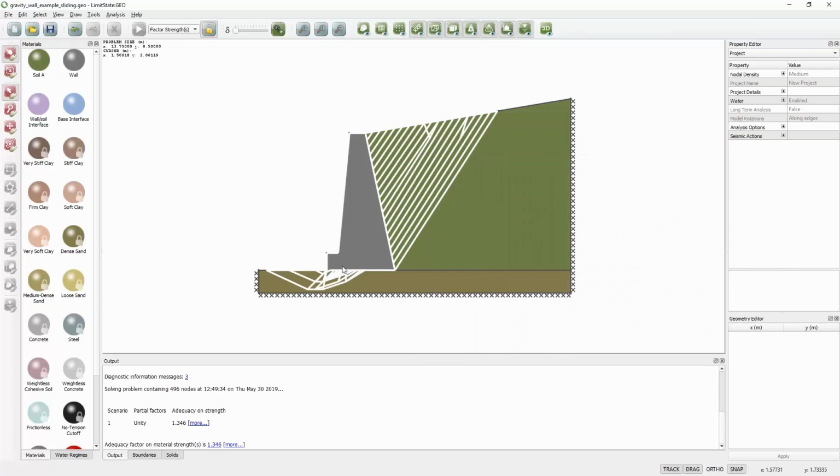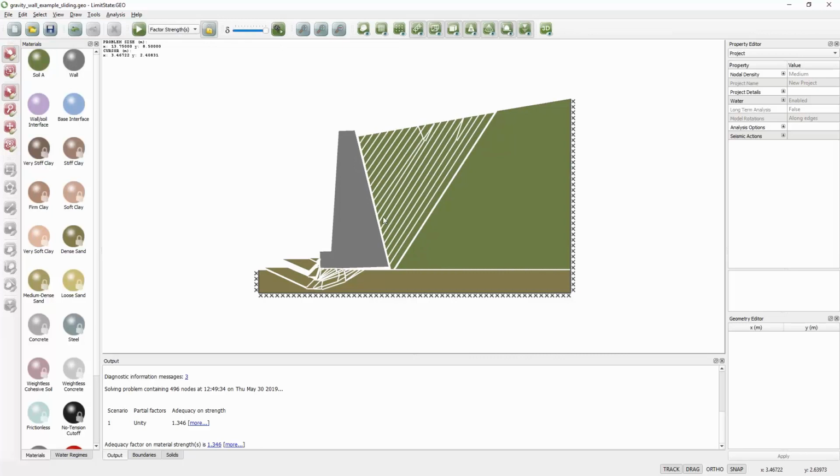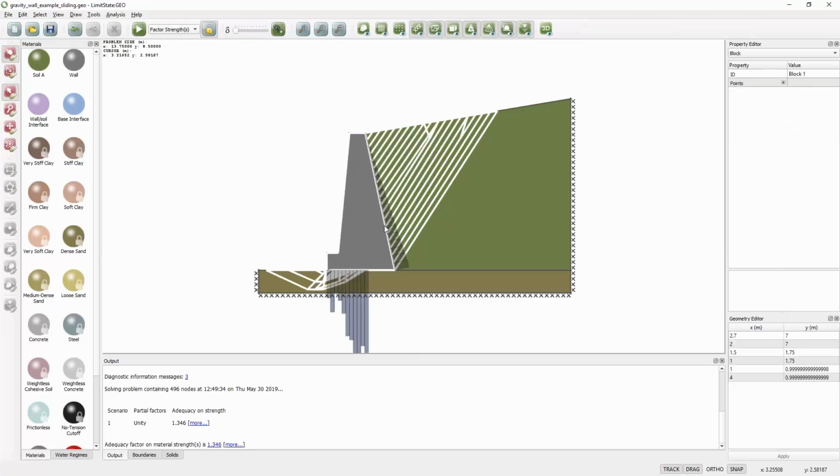And in this case, you can see that actually we've got a little bit of base failure as well, so it's almost sliding, but the wall is starting to tip forwards due to that base failure at that particular point. But the number is still bigger than 1, so that means that it is stable. And if I put that back, I can also, if I click on here, I can see the pressure distribution, so we get a little histogram of pressures, and average stresses are displayed as we go down. So these increase with depth, as you'd expect, typical sort of active pressure distributions.